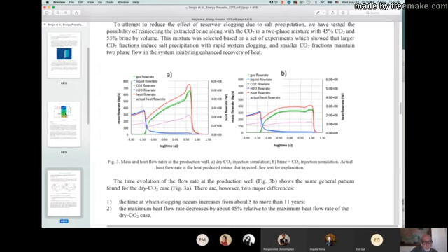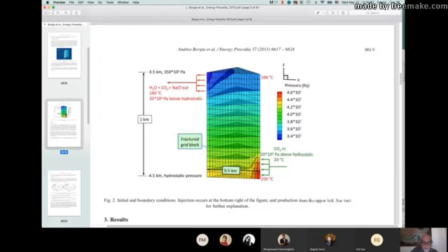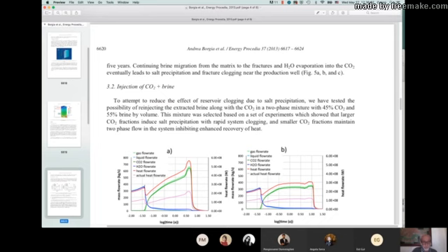And the reason is, and let me explain it going back here, as you develop your CO2 plume, since the CO2 is so low viscosity, the pressure drop is only in the water. So as you develop your CO2 plume that goes towards the producing well, the distance over which you have the pressure drop decreases, and therefore you produce more. And so this is your production.